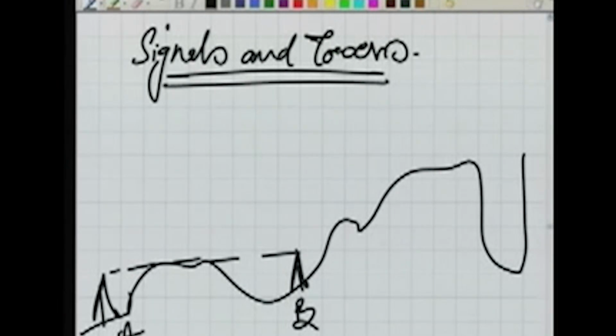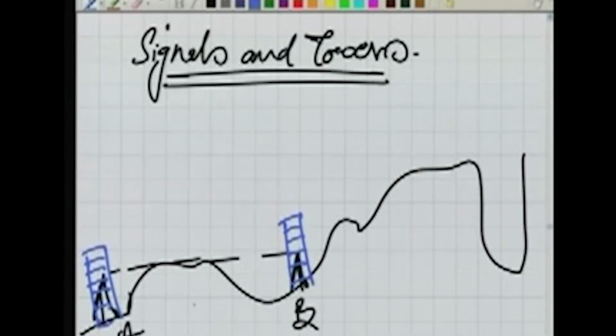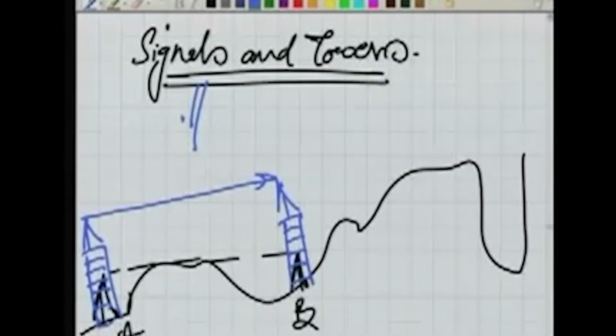If they are not intervisible, what we would try to do, we will try to erect a tower here, because we want to have these two definitely as triangulation stations, because our triangulation figure which is formed is very good, the angles are well conditioned as well as the requirement of the field, but this line is not intervisible because of the intervening ground. So what we would like to do, we would like to erect the tower so that I can keep my instruments or the theodolite on the tower and I can then take the measurements. So there are various kinds of signals which we use in triangulation as well as the towers.